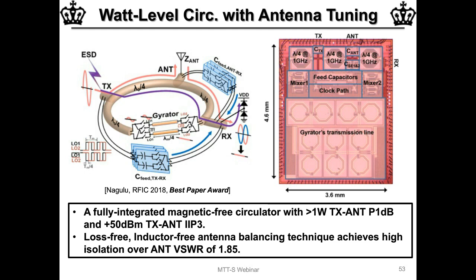That being said, as I mentioned in my last slide, the one mechanism that can still contribute to noise is the phase noise of the clocks. The phase noise of the clocks can degrade the noise figure, particularly when it mixes with a powerful transmitter signal, which is essentially a reciprocal-mixing-like mechanism. This is something that we have observed in the design, and we're actively working on both a theoretical formulation to understand that, which is almost done and should hopefully be submitted for publication soon, but also circuit techniques to mitigate that.